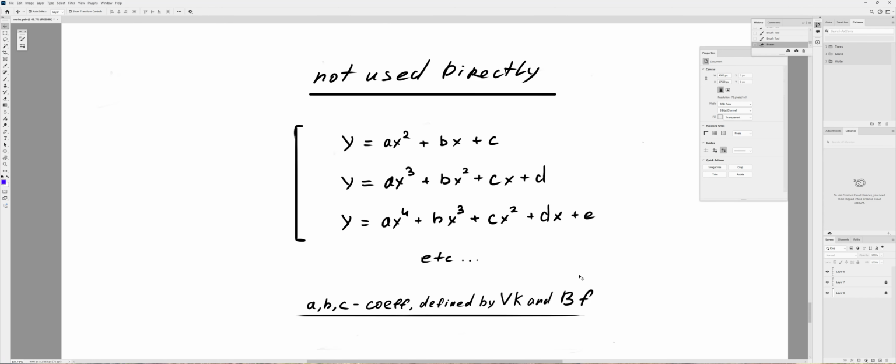So you will have this unwanted torsion, and the more control vertices you bring, the more and more of them affect the curve at the same time. So it becomes almost impossible to accurately construct the curves without any hiccups, dimples, sudden torsions and stuff like that. That's why Alias and other CAD systems limit the amount of derivatives you can work with at a time.